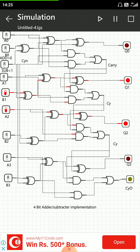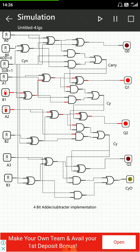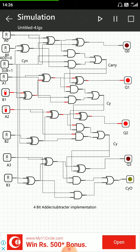and you can see addition is performed because the toggle switch we have used for addition is at low logic, that is 0. So the output is 0 0 1 1 0. This is equivalent to decimal 6. So 4 and 2 after addition is 6. So hence 4-bit addition is performed.